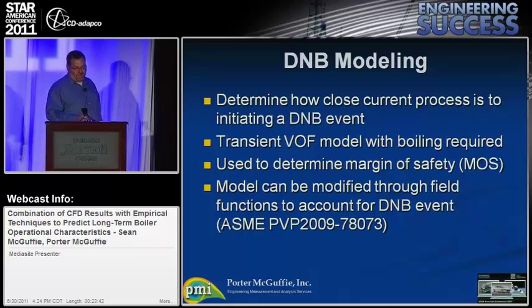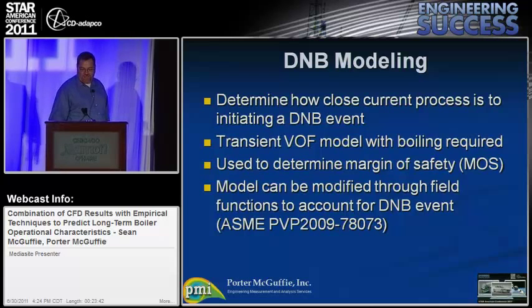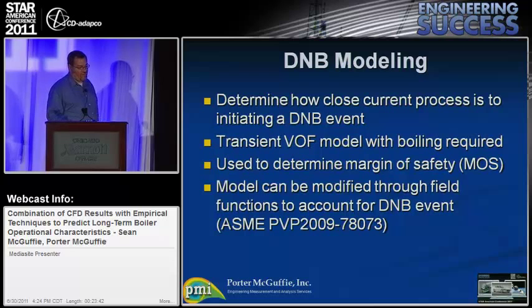And then the last thing that I'll mention, and I have the reference of an ASME paper that I'll wrap up with also, we did develop the technology to modify the model through the use of some fairly complicated field functions to account for the departure from a nucleate boiling event and to predict what the maximum rise in tube temperature is versus time.